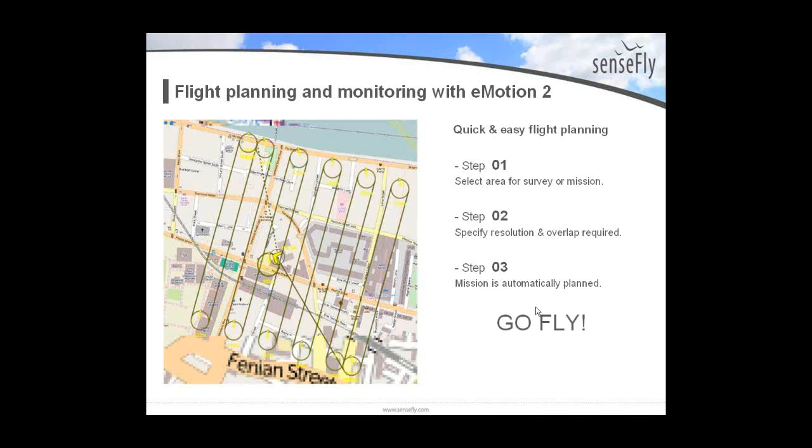So once the mission is planned and you have everything in there, you upload it to the eBee, and then you go fly. Once you've loaded up the flight plan, you hold the eBee by the 2 wings with your hands in front, at a level position. You shake it back and forth 3 times. That will start the engine.